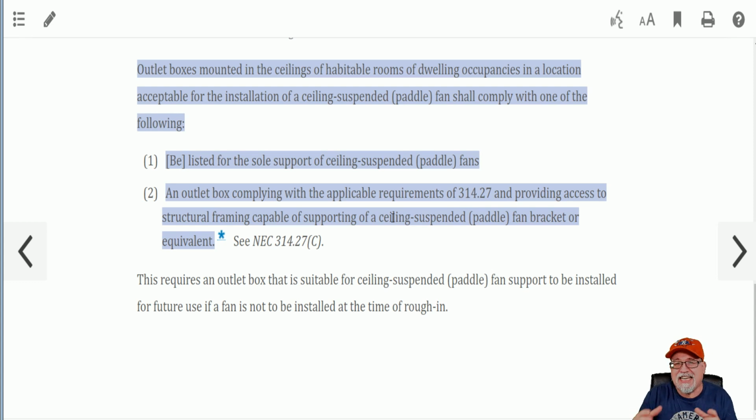Okay, so you can buy these little kits. That is going to be one where people are going to be very touchy about this rule because some people will say, well, if I say it's in the 1st floor and I have a 2nd floor and I have the closed ceiling, couldn't I take that down and then take that box out and put in one of those twist style? That's what they're going to argue, that you could do that. I think this rule was meant to say, no, those you're going to put a properly typed, sole-supported type ceiling fan box.